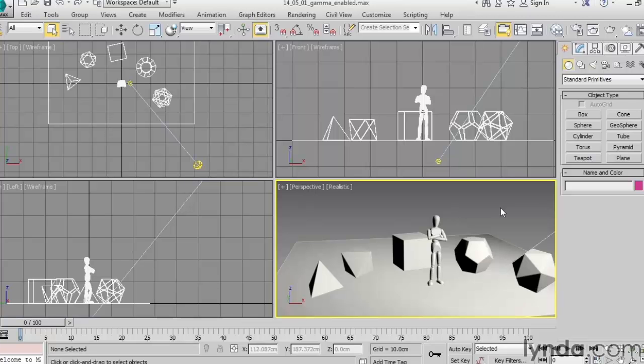Standard lights already sort of have gamma correction built into them, but photometric lights add together linearly, and contrast curves are applied at the end of that addition process. And that's done through an exposure node, or exposure control setting. So basically you need to have gamma turned on or off depending upon which type of lights you're using.